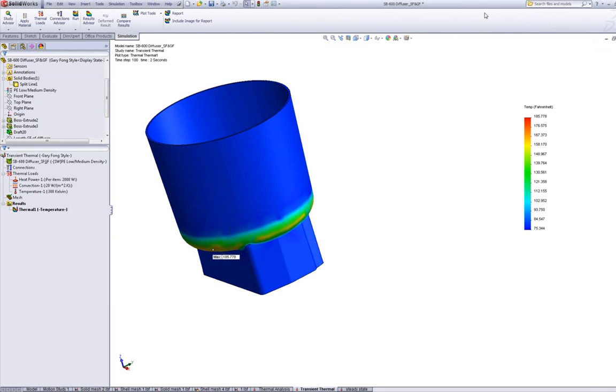Like I mentioned before, after this particular flash, assuming that my setup was accurate, all of my assumptions with applying my 3,000 watt power, only having 2,000 watts affect the material, and applying this particular loading, this is my result. So if those assumptions are correct as an engineer, then my model should perform. I should not have a massive failure to this part thermally.